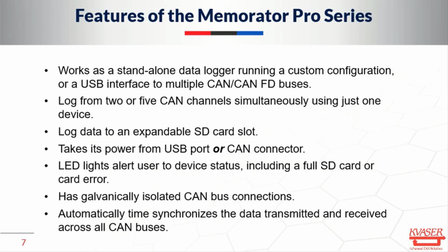They do have LED lights that indicate the device status, including an SD card full or an error, and the LED lights will indicate that it's connected through USB to a PC as well. There is galvanic isolation between the USB port and all of the CAN channels. The device automatically time synchronizes the data transmitted and received across all CAN buses, so their internal clock will time synchronize all of the data that it logs with an accurate timestamp.